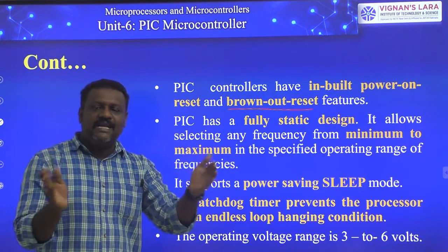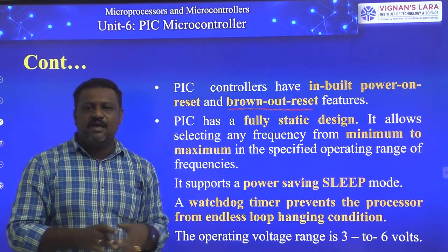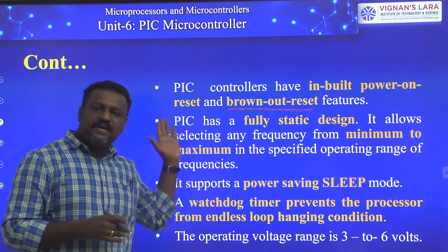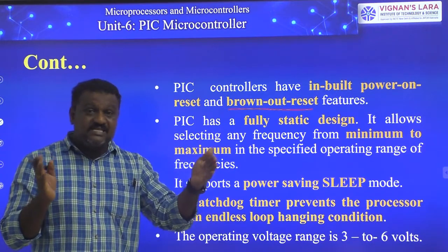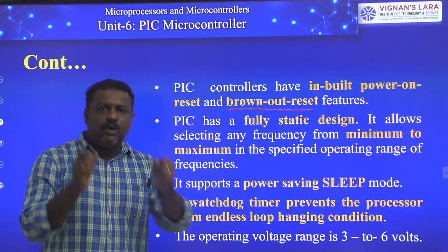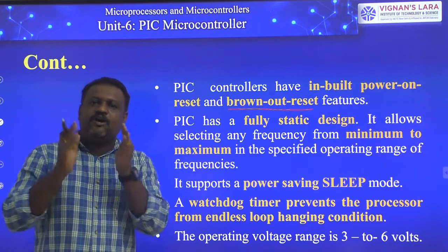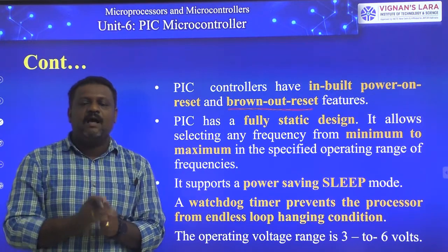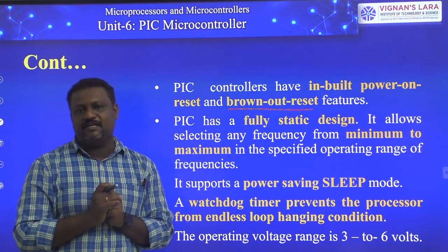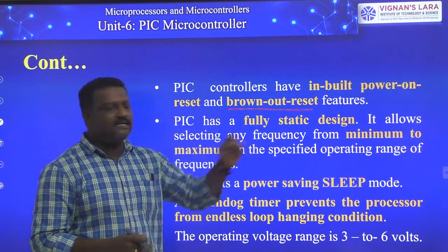We can select any frequency in that range for operation of the 8051. In a similar way, the PIC controller also supports a range of frequencies. For its operation, we can pick one frequency in that entire range, and your controller operates with that frequency until you modify or change it. So that indicates PIC has a fully static design.